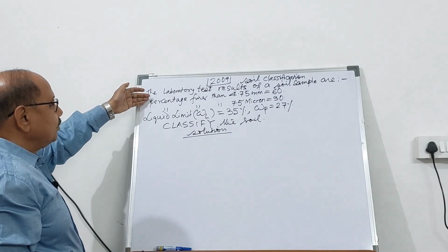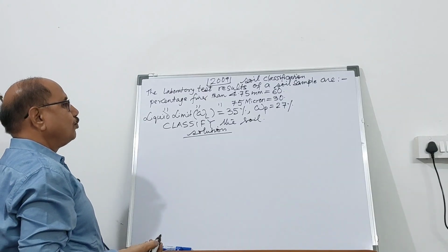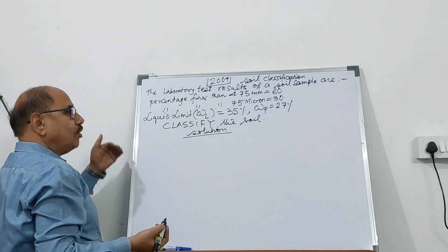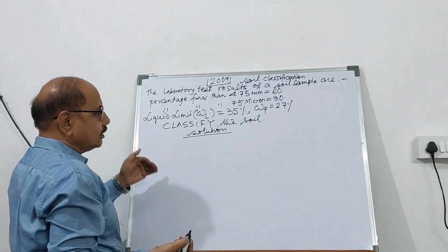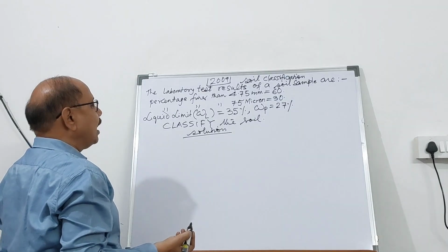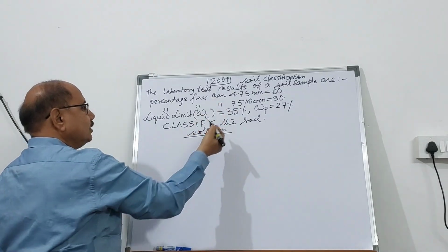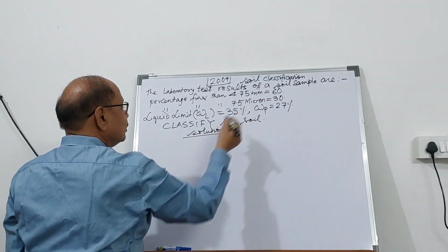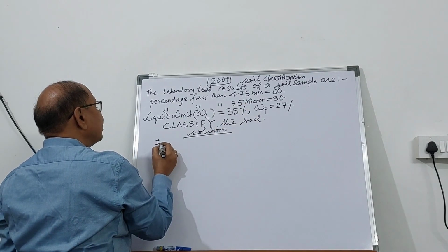Now, the percentage finer than 4.75 mm is all fine aggregates, that is sandy particles, and also the fine particles. So that's given to you as 60%, and the percentage finer than 75 micron is all fines, that is fine grained soil.